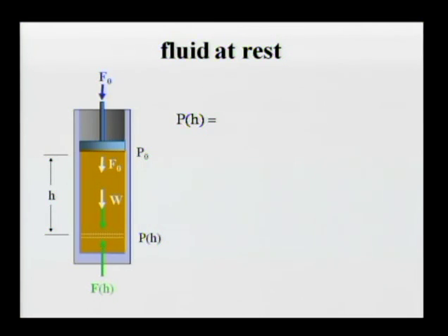If the center of mass doesn't move, what does it mean? That the sum of the forces exerted, which forces? External forces. The sum of the external forces has to be zero. How many of them do we have here? Three, correct. So the sum of those three forces has to be zero, which means that the force which is exerted by the slice is opposite to the sum of those two. If I think about magnitudes, both forces, this force and this force, are exerted in the vertical direction. So the magnitude of the sum of those two forces is equal to the sum of magnitudes of the two forces, right? Do you see that?